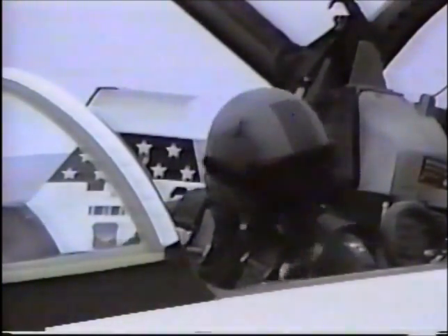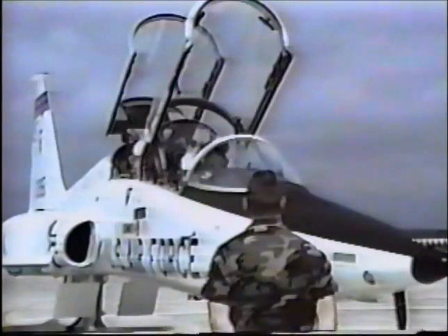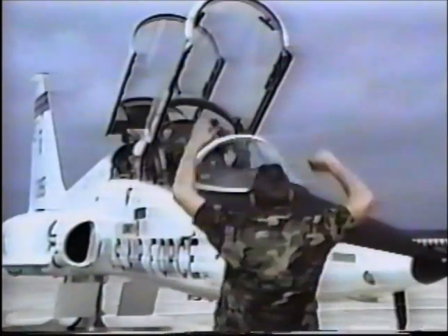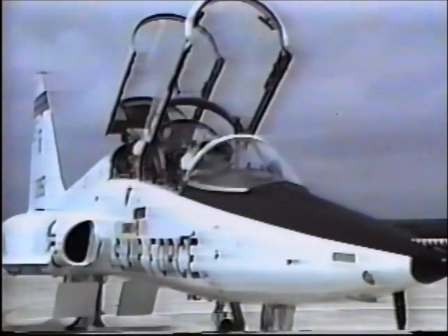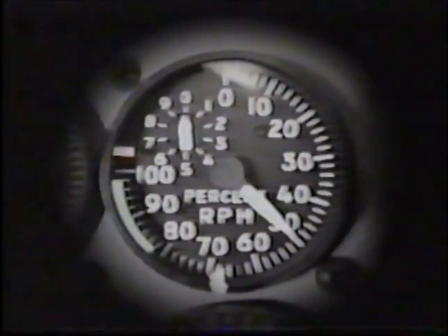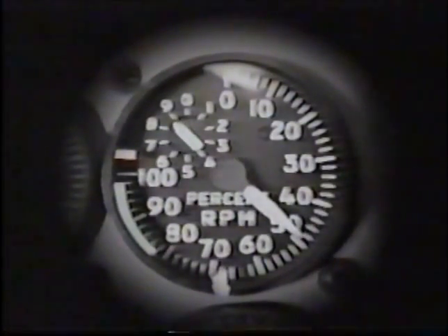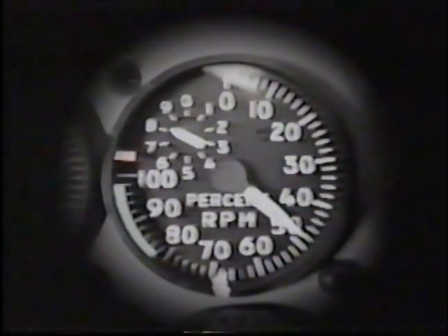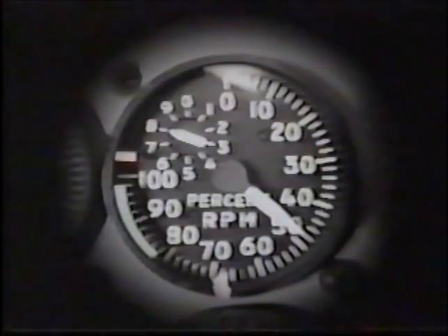Continue to clear and signal the crew chief to divert the air from the right engine to the left engine. Hold your hands clear until you're ready to start the left engine. If the RPM on the right engine was slightly high when you check your engine instruments, it should return to idle limits as the air supply is diverted to the left engine.